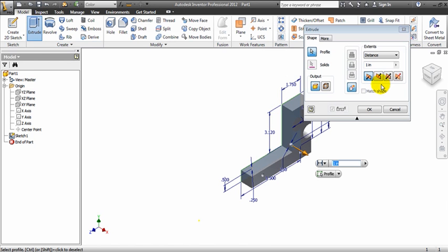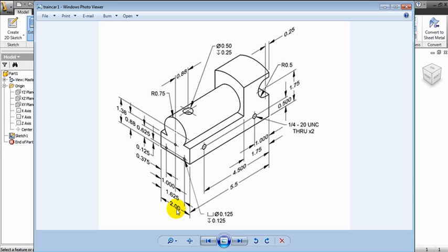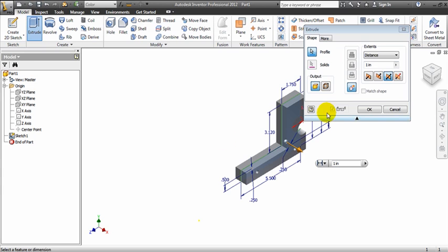And I'm going to extrude it in both directions just so that I have something going right down the middle, or so that I can mirror things to one side or the other. So I chose symmetric. And this thing is 2 inches wide. From here to here is 2 inches, so I'm going to create 2 inches for my extrusion.